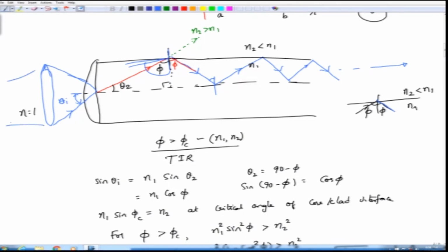So, this would be the mode coming in from the laser, and it has to be coupled and focused onto the core. What should be the cone angle? What is the maximum cone within which the light coming from the light source will be accepted and guided by the core? This is called the acceptance angle, or sometimes the numerical aperture. Let us derive an expression for this numerical aperture by writing three laws.